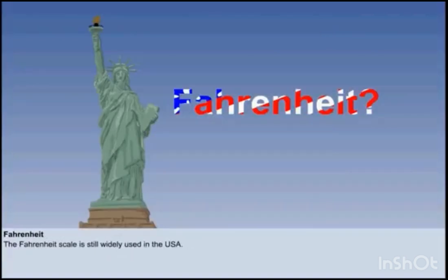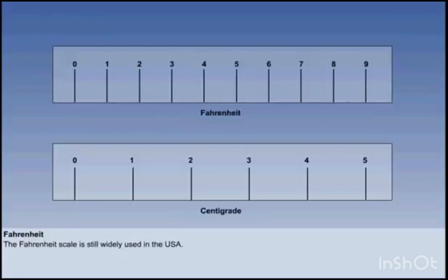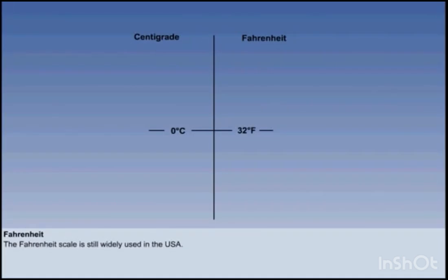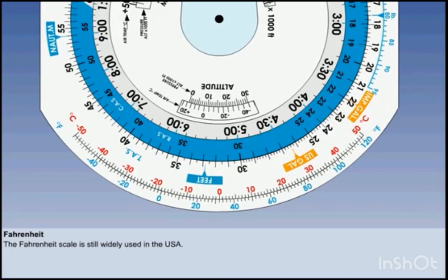The majority of the aviation world uses centigrade or Celsius as a temperature scale, but Fahrenheit is still widely used in the USA. There are 9 degrees of Fahrenheit temperature rise to 5 degrees of the equivalent Celsius rise. And 0 on the Celsius scale is +32 Fahrenheit on the Fahrenheit scale. There are formulae for conversion, but for simplicity, use the temperature conversion scale on the CRP5.